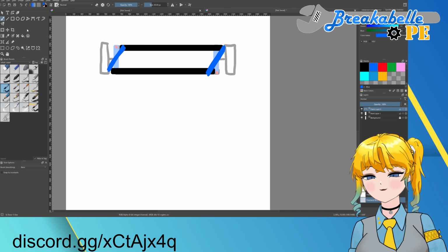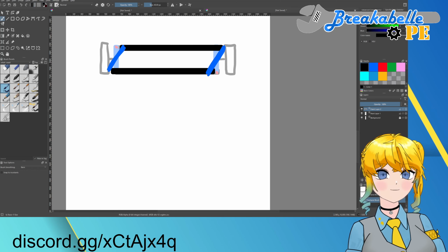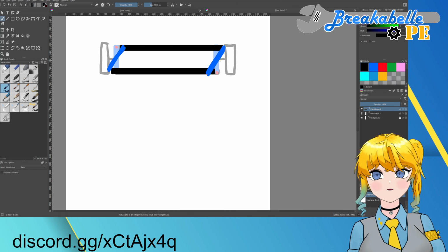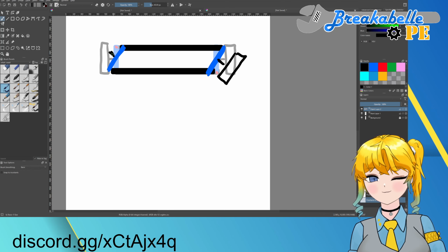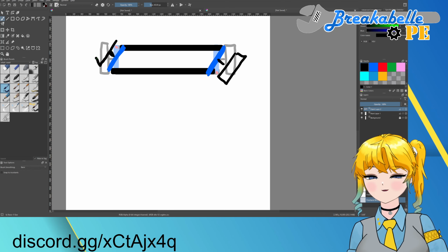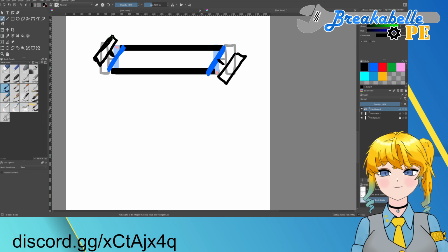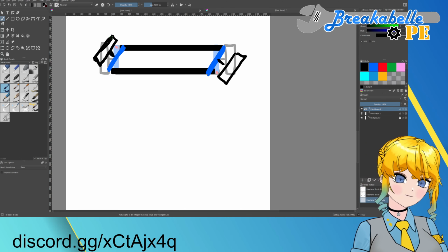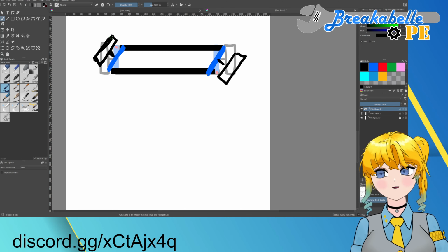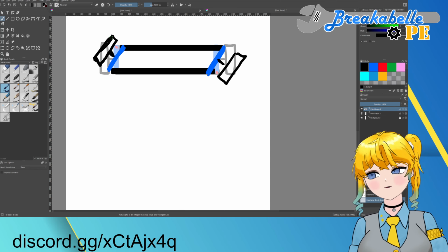Right. And then our wheels are now turned. That's what intuitively makes a lot of sense, to turn both wheels together, right? You make this parallelogram linkage, and that turns them both at the same time. That's how you make sure that they don't be miscoordinated, right?